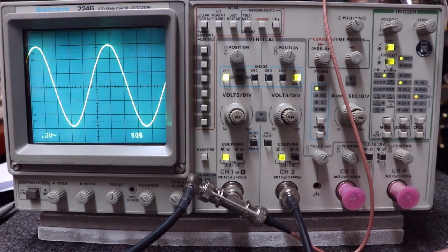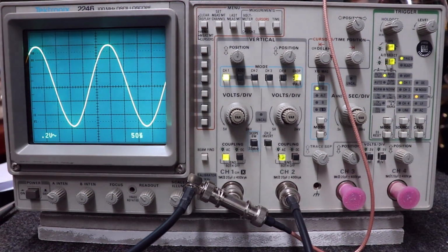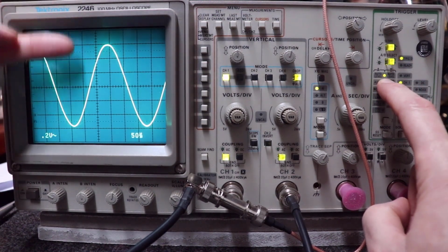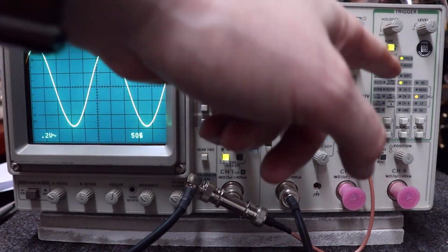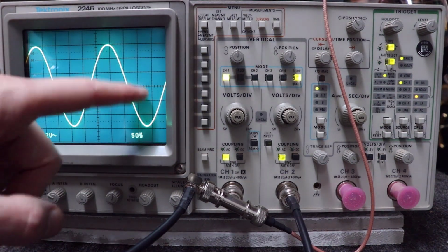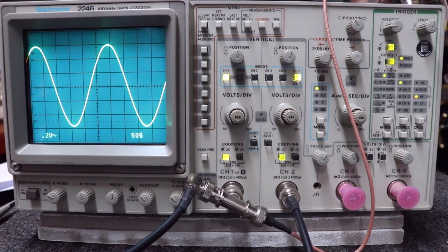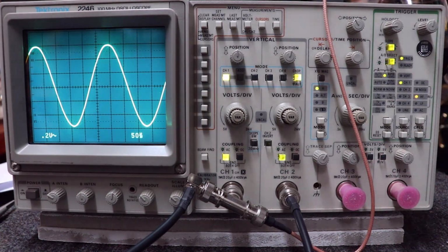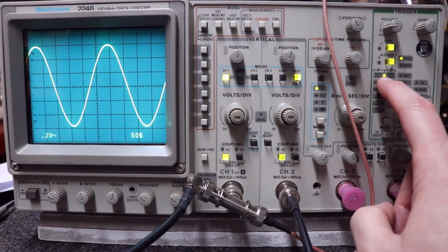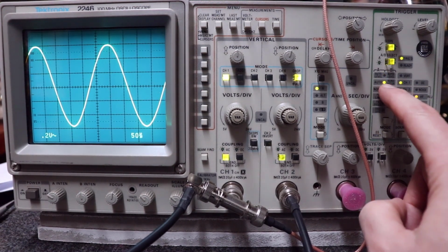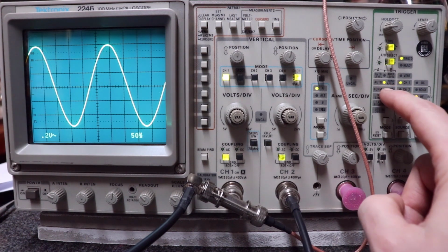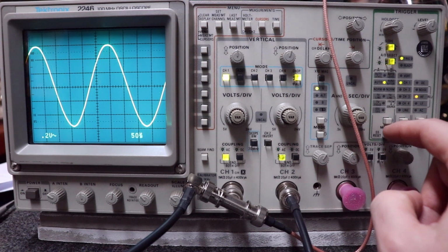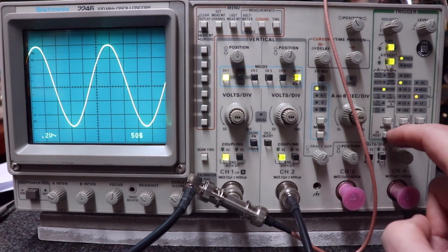But if I get it back on channel 1, when you have a sine wave, most of these scopes, like right now I've got it on auto level, it'll find a level and it'll lock on it. This auto sensing piece is pretty darn smart, and it'll lock on just about every time. Here's the good news about all these little buttons and knobs over here. So this here, auto, then you can go down to auto level. Normal ties back to what's on this.